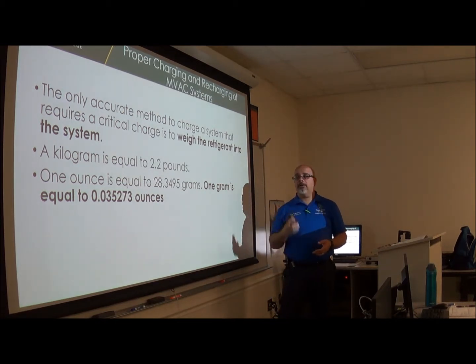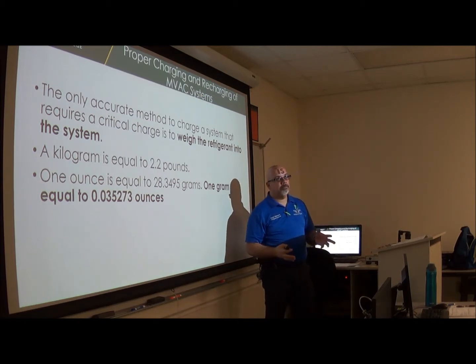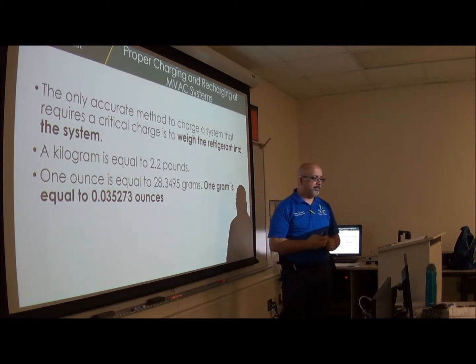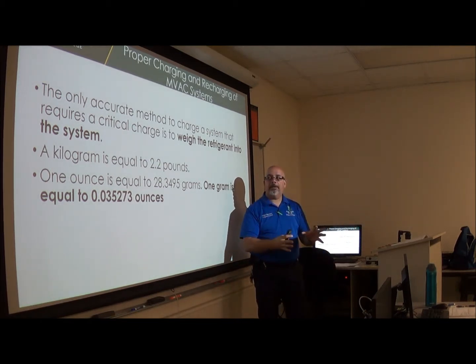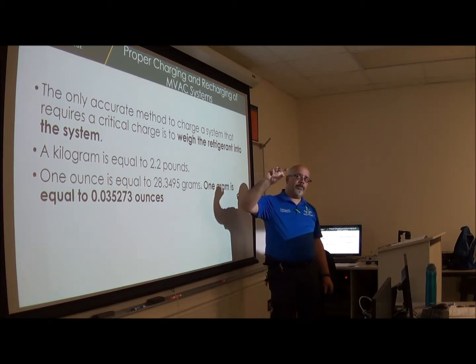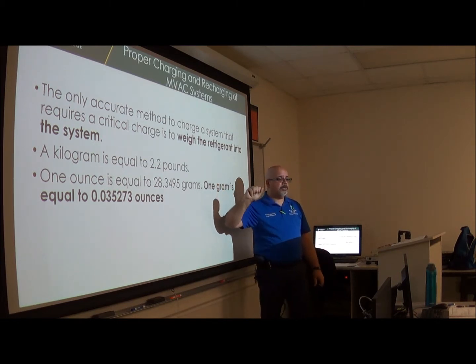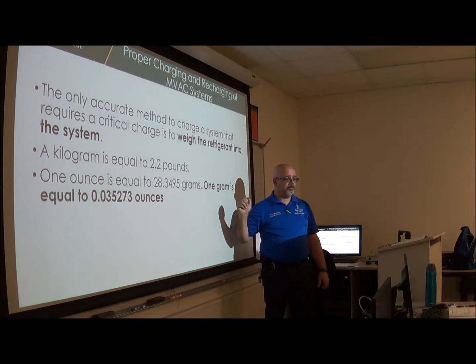Because before, we would say, okay, this car uses 2 cans because it uses 2 pounds or whatever, something like that. So it'll use 2.5 cans, 3 cans, and you'll fill out that system. New modern vehicles, now the label that's on the hood says that that car is only going to use 1.2 ounces. Oh, okay.